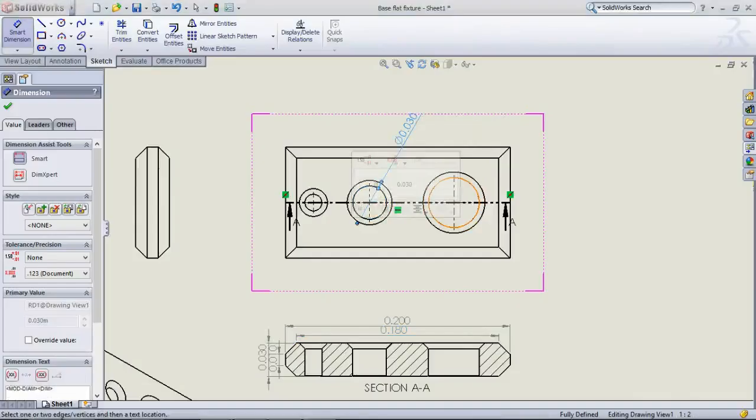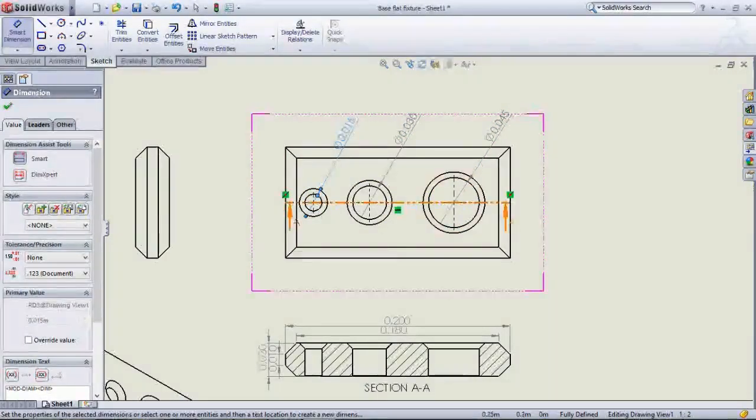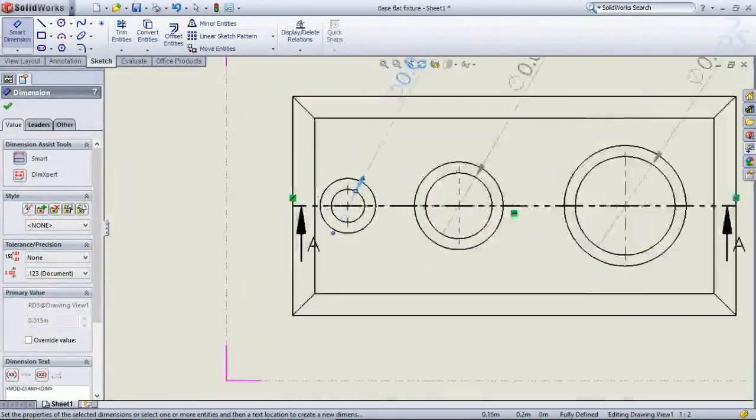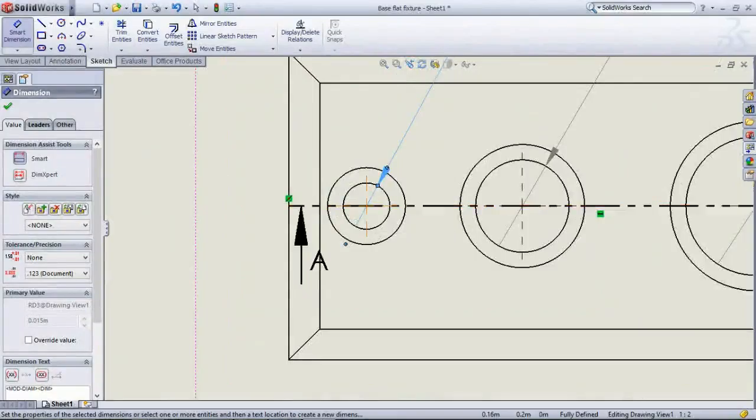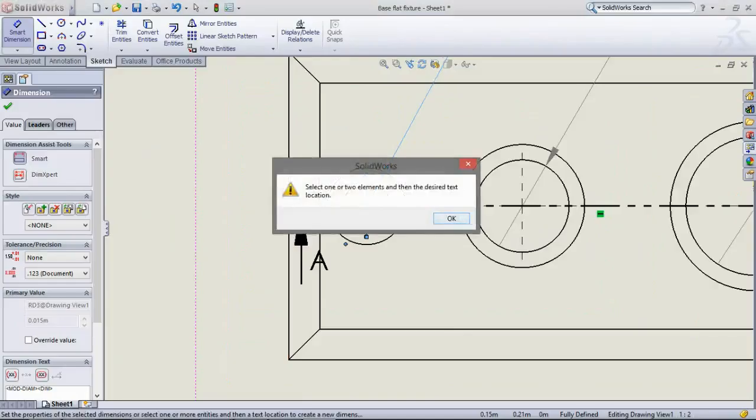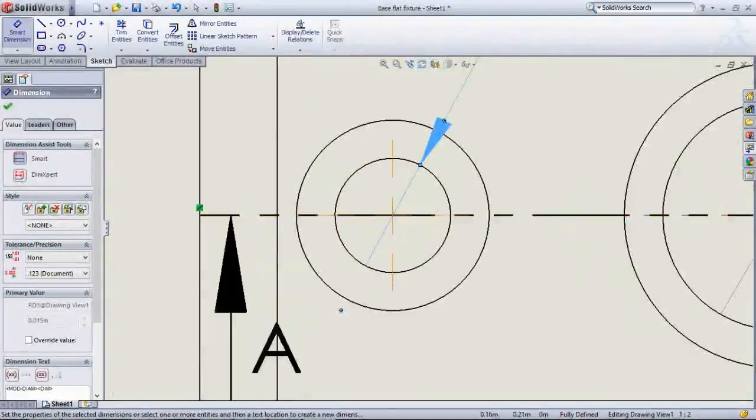The drawing you design should be understandable enough to manufacture the part perfectly, with your idea of the stock size, what raw material stock size will be considered, and what operations you are going to do: milling, drilling, and sometimes boring is required. So you have to include what operations you are going to do.